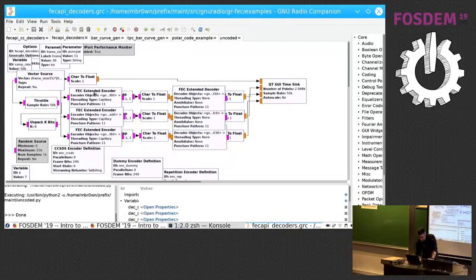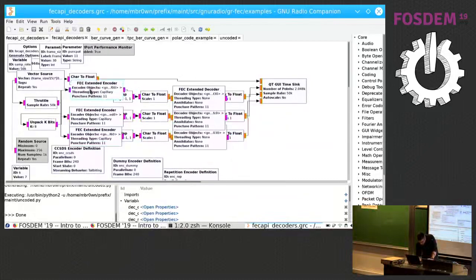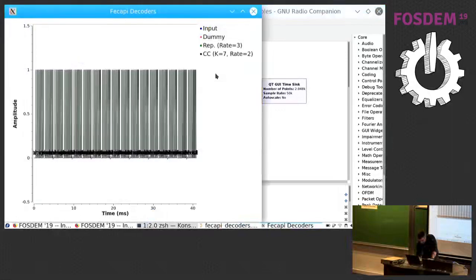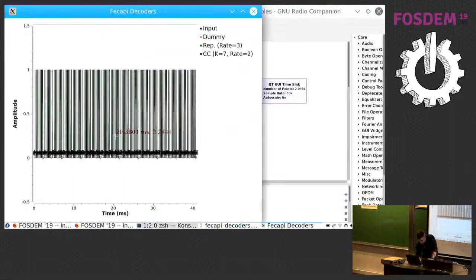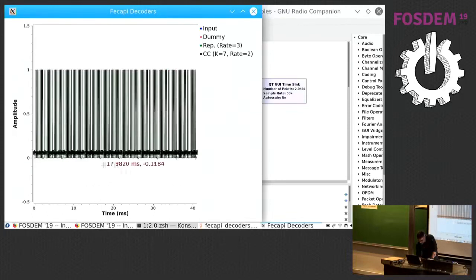So we take bits, we encode them, we turn them into BPSK symbols, the +1, -1 representations of our bits. And then we decode those, and then we just look at the result. We have 3 different codes here, and you will notice that the block is always the same, even though we have different codes. So let me just run this real quick. It's not the most enlightening visualization here, but it is just nice to see that things are obviously working out. The random bits that I'm generating are coming out identically in all 4 cases.